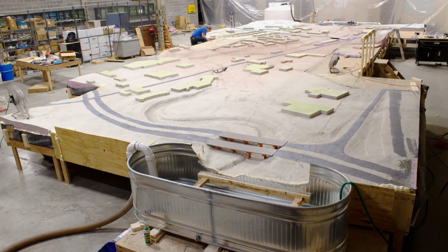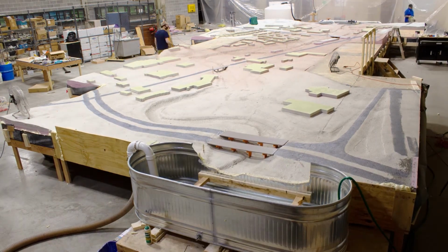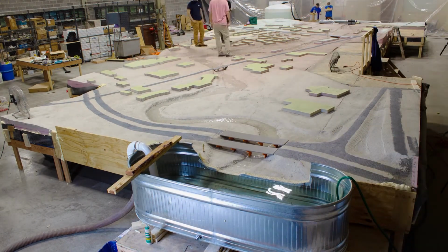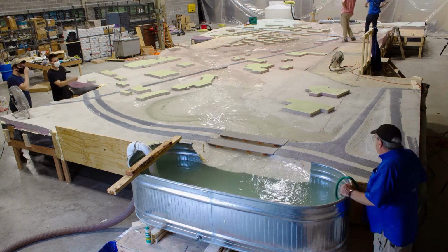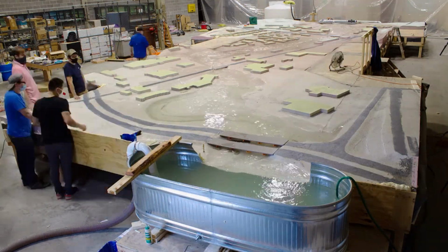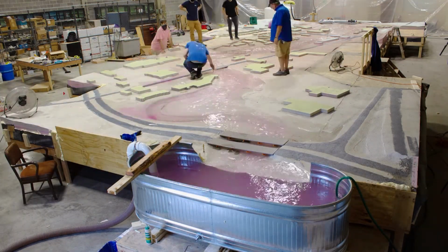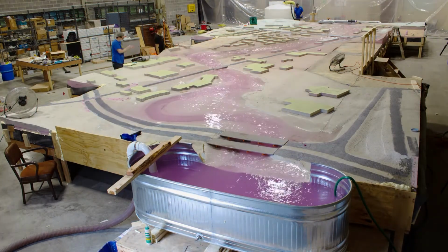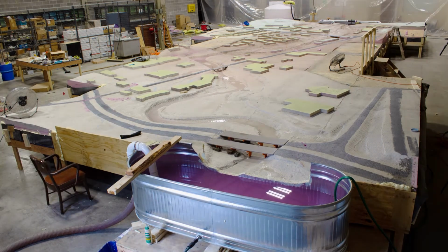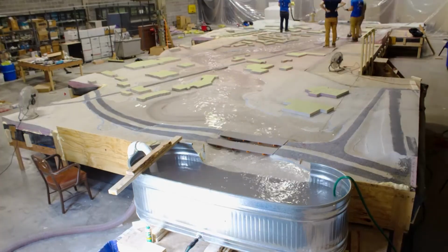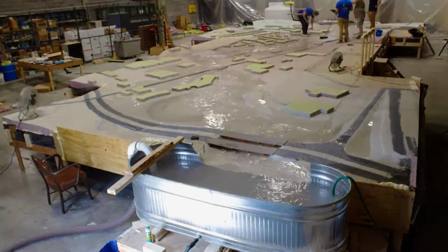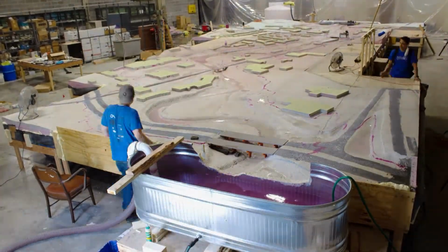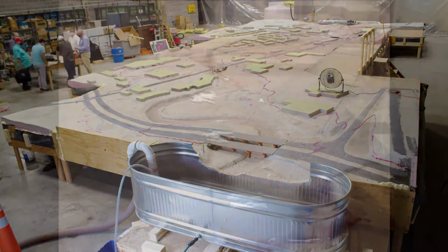And so this physical model, the initial shakedown test, if you will, was completed by just running a series of flow events through the model to see how it reacted, to see if there were any leaks, to see if there were any issues that we noticed that didn't make any sense, and to go ahead and correct those. In this particular case, the shakedown test went extremely well. We did not actually have any major problems. And so that allowed us to very quickly move into the calibration phase.